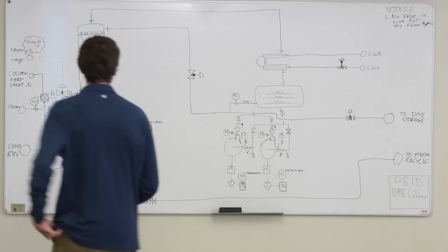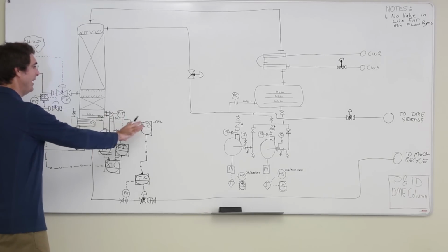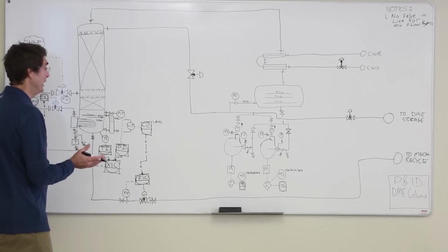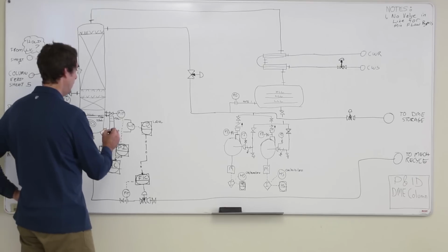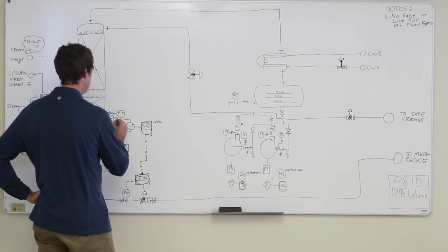So if you look at some of the safety incidents that have happened in the past, some of them have been because level transmitters have failed or read wrong, and so forth. And it's not a bad idea to have some sort of redundancy in this game. So putting some level switches in is not a bad idea, probably. Also, a sight glass wouldn't be a bad idea as well. So we have this stilling pot, and let's put a sight glass across it here.